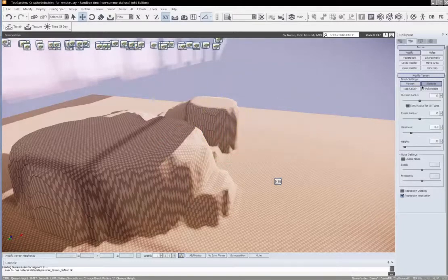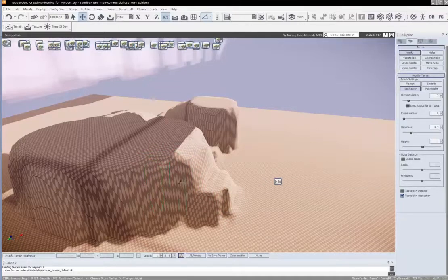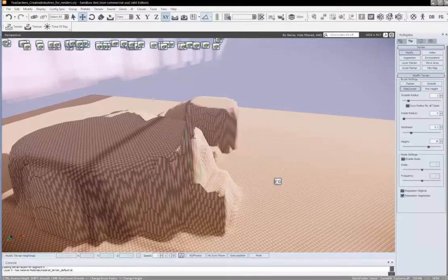You can put it on rise / lower. What this height value here is, is the scale that it's going to move the land. So it's going to move it all up 1, no matter where it is. See how it's moving it all up? So you can move everything up. Or what if I want it up a bit higher? I can put it up to 20, and now everything's moving up a lot quicker.